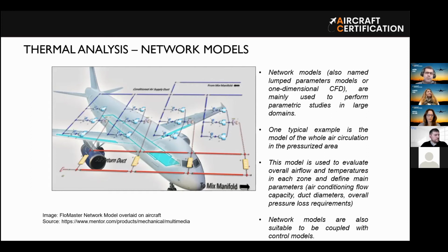So network models are basically, if you think of a hand calculation, normally it is like a network model. Okay, if you are in a room and you consider the main heat loads in that room, the sun and the electric lights and so on, and some ventilation, you can do some hand calculation to see what is the average temperature of that room, and this is a network model.